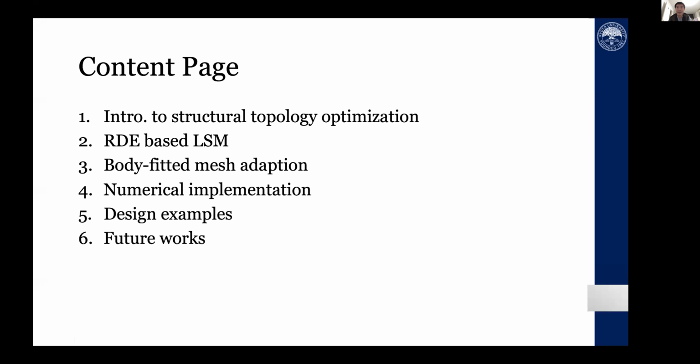Okay, so here is the outline of today's presentation. First, I would briefly introduce the latest application of the structural TO technique in the industry. And then we overview our level set topology optimization methods based on the reaction diffusion equation. Next, we show several nice features of the body-fitted adaptive mesh technique integrated in our framework. And after that, we quickly discuss the numerical implementation using FreeFEM, PETSc, and MMG. Finally, we show several classical benchmark optimization test cases.